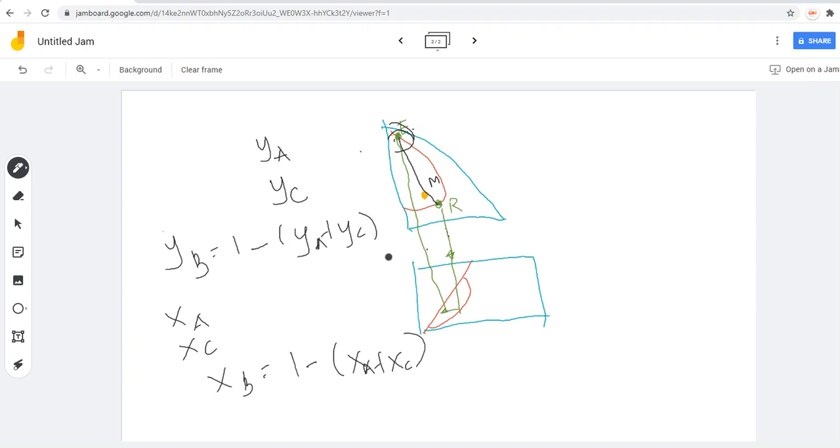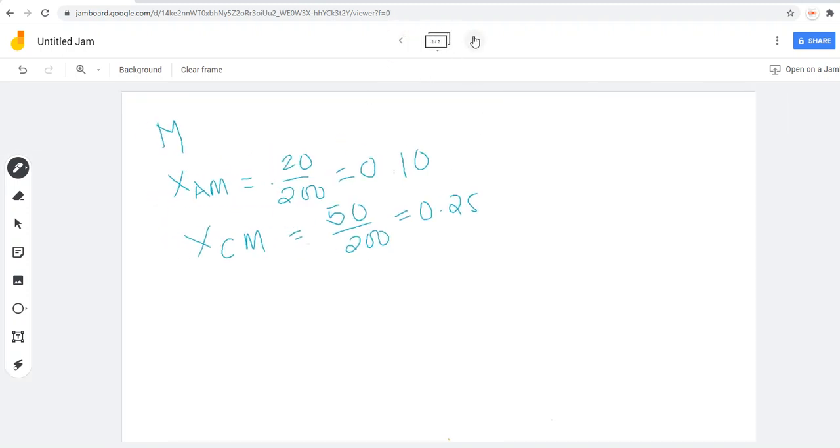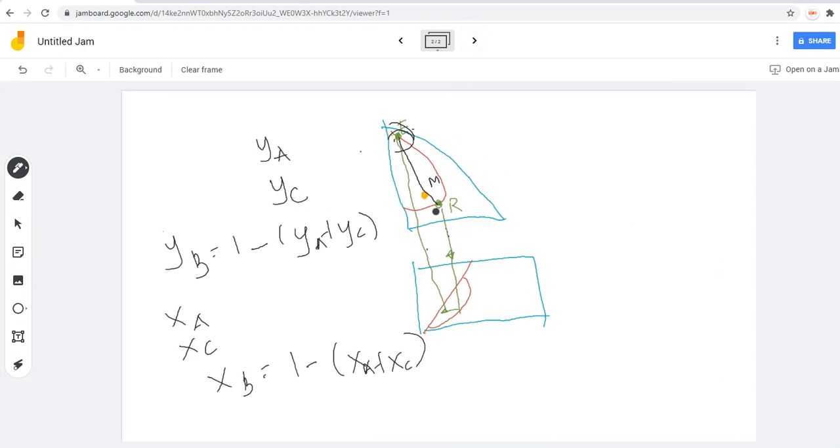Now this one allows you to graphically, just given only the composition of the bulk phase, actually it's not given, you computed it here, determine the composition of the raffinate and the extract layer after the mixture was equilibrated, and how the two separate equilibrium data was linked so that we'll be able to get this particular composition that we are interested in.